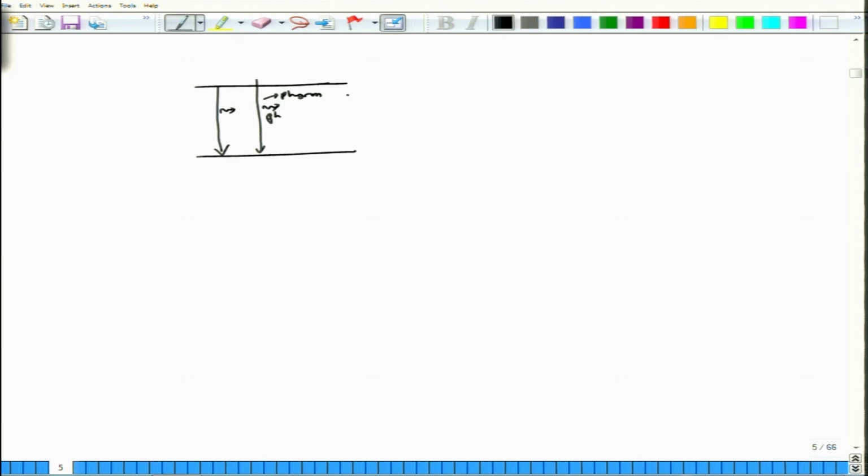And you might have some acceptor levels or donor levels sitting here, and these levels are the traps, as we would call them, and they are temperature dependent. Okay. So, electrons can jump first to them and then jump to another trapped state and then finally jump back to the holes and recombine.